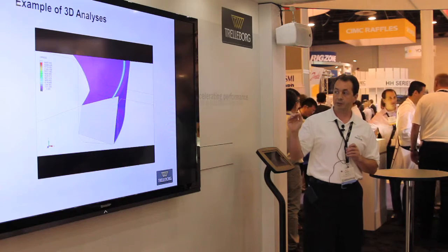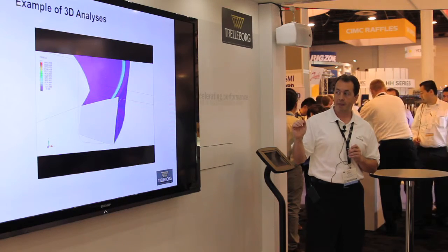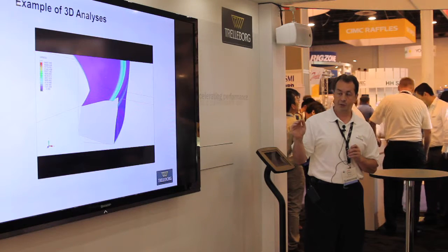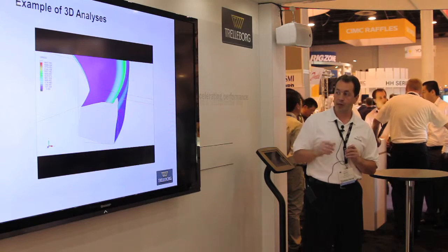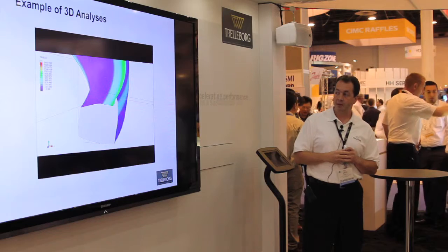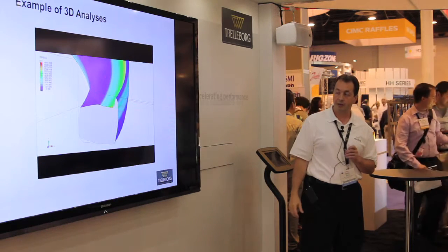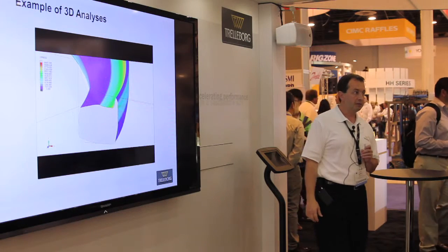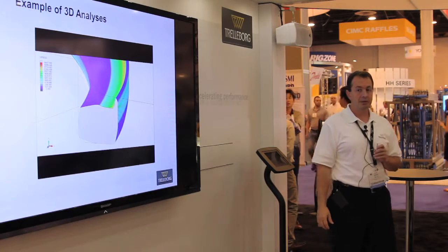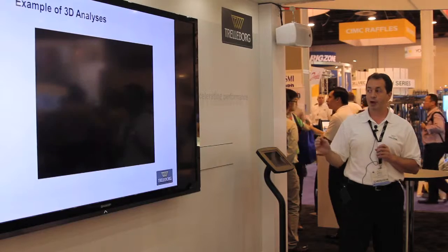So as we close the valve further, which will load here in 1 second, you can see that the stresses begin to increase in the seal. We can also visually see how the seal reacts to the valve closing. In this case, you can see some of the seal is being pinched or extruded up the side, and that's an instance where it is not an optimal application. So we would go back and redesign the seal to make it function properly in that application.